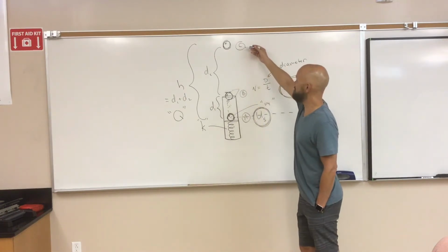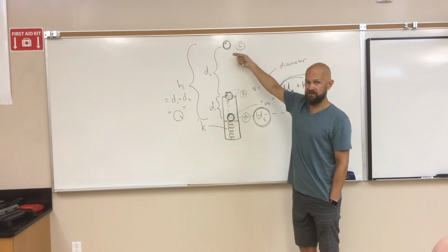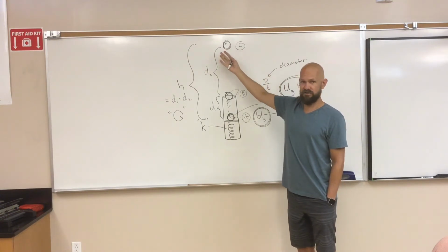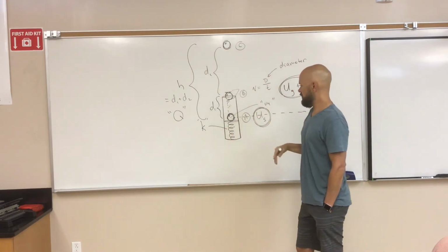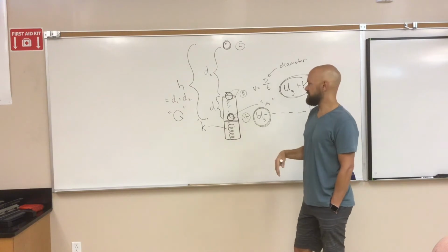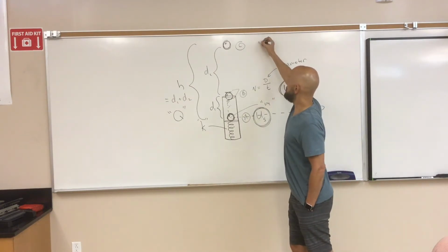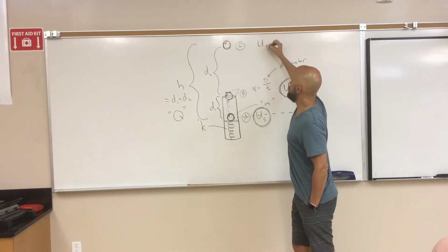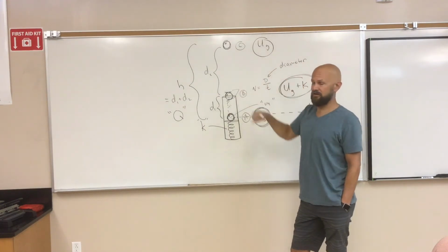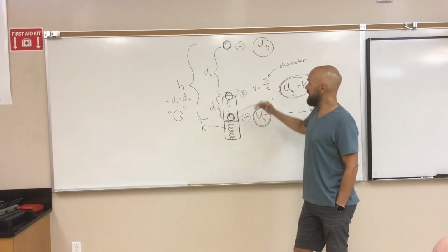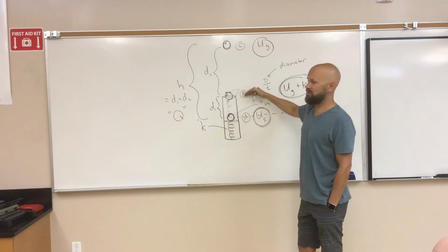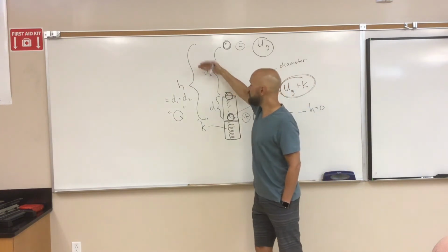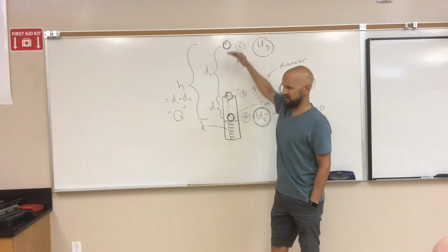Okay, and then at point C, there's no kinetic energy, it's at rest. There's no energy stored in the spring, it's already released its potential energy. And so all we have at position C is gravitational potential energy, and we'll calculate that. And if the energy at C matches the energy at B, then we can say that there's no Q developed as it moves from B to C.